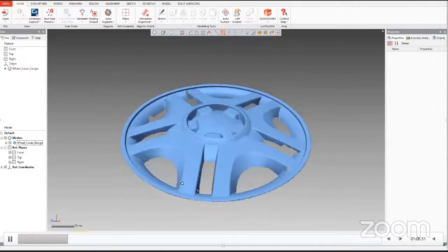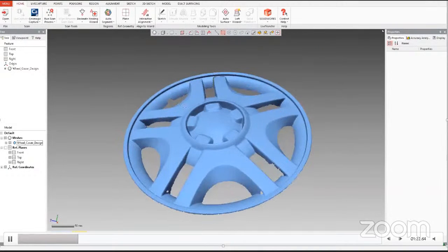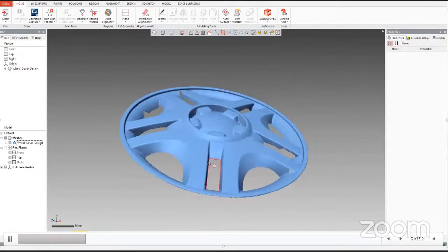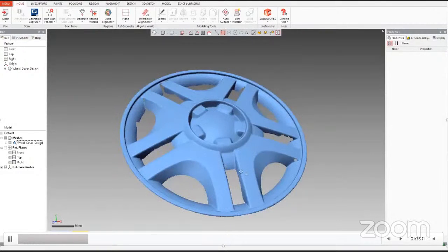We can see there are patterns, there are 5 ribs, and they are copied into 5 patterns in a circular way. And in the middle, there are some boxes also patterned in a circular way. So instead of going to each section individually, we can perform the circular pattern option once we have found the central axis accurately.